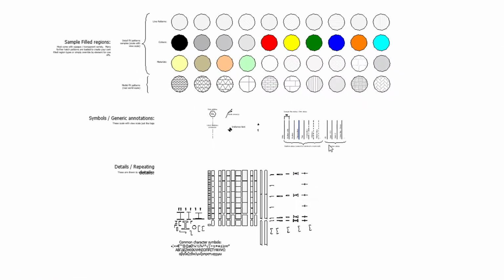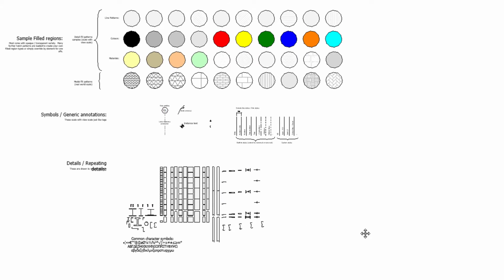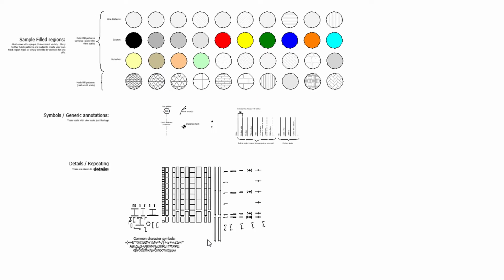Once that's loaded, you will see that by default it goes straight to a drafting view. This is the standard setup for the University of Leeds drawing template, and on this drafting view it details some of the elements and hatching styles that are associated with 2D drafting, and that's what we're going to be concentrating on: 2D drafting of a portal frame section.